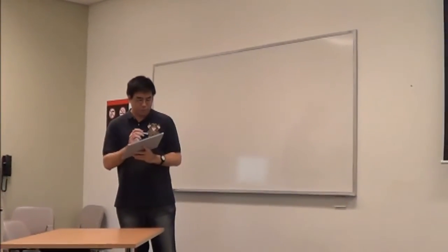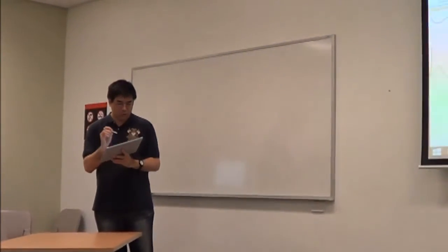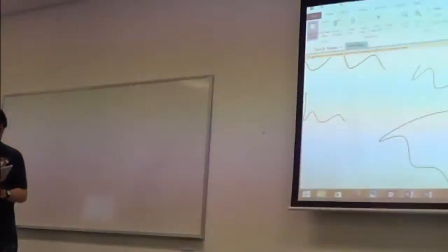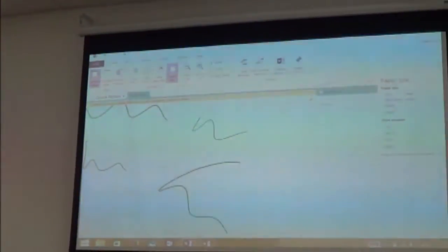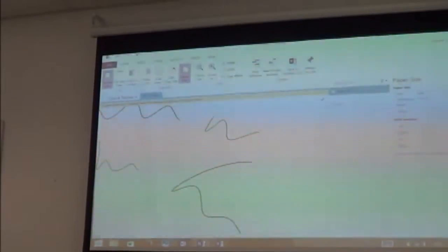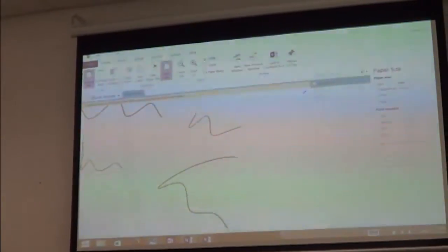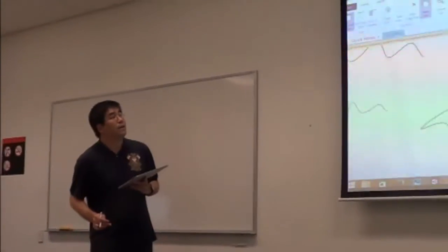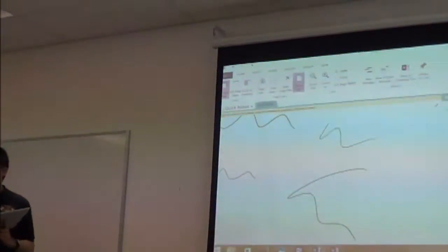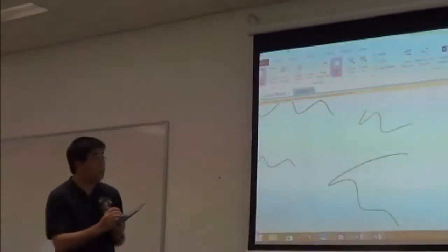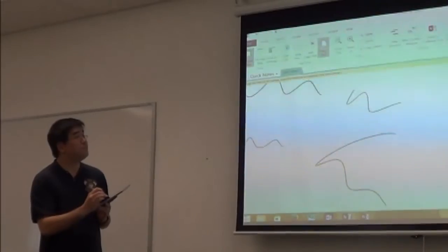So what we need to do is to go to View and go to Page Size. And page size, as you can see, it's on the side there. Okay, page size. Currently it's set to auto. Now the offender, the setting that's causing this problem is this top and bottom setting.